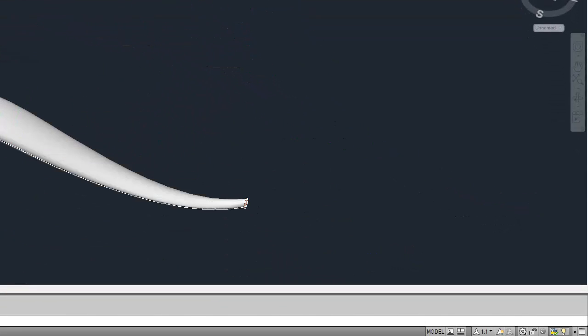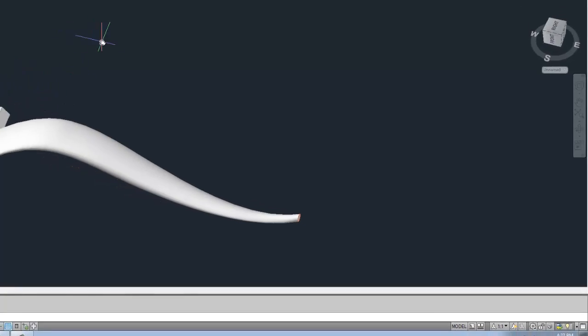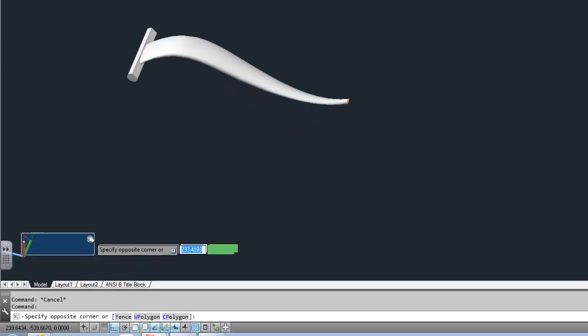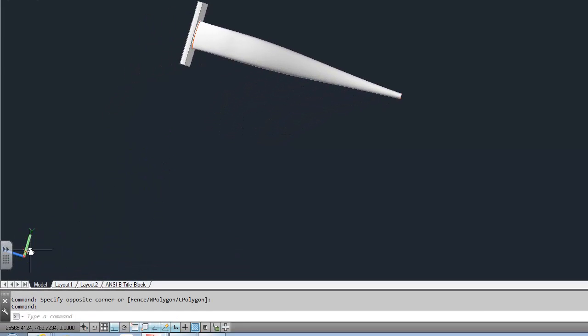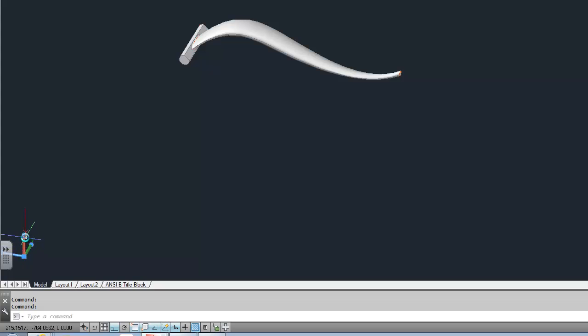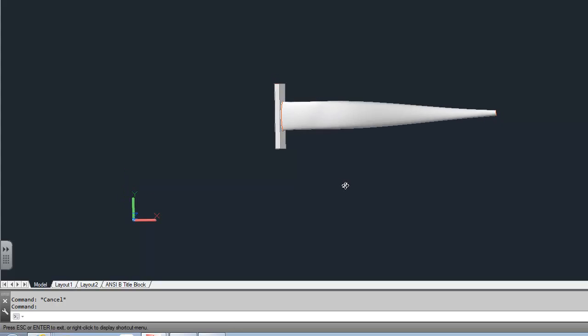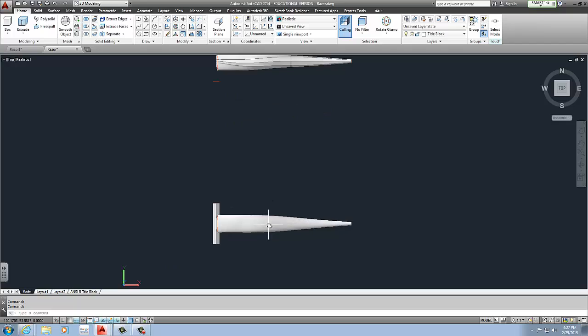But for this also, we can also place a text into it. I'm not sure if you guys learned this before, how to do this, but I'm going to teach you that. It's very simple. What you want to do is make sure you are working on the X and Y coordinate system. So right now, if I'm looking upwards, it's on Z and Y. That is not what I want. I want X and Y to be facing the top of the razor, like so. So if I'm looking from the top, and I've got the X and Y as shown, from there we go into annotate.